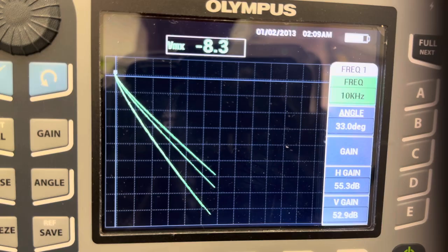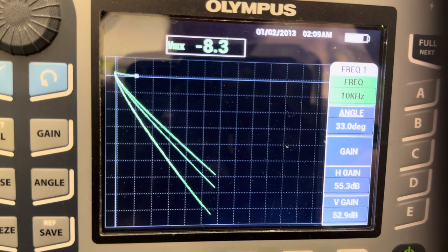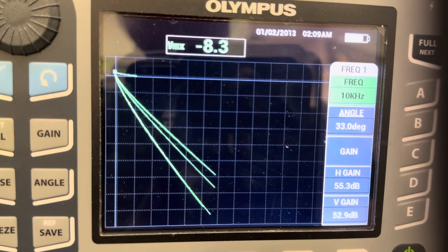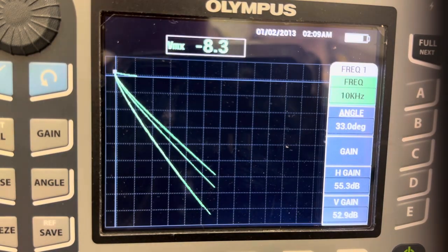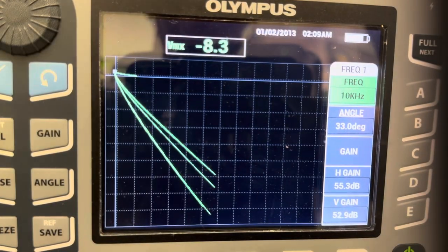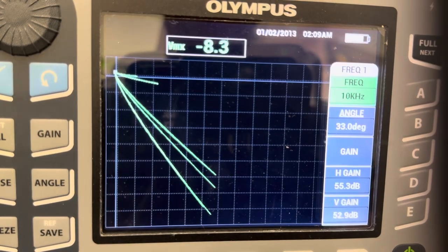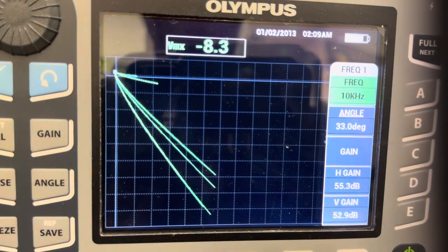But when I try to separate low conductivity materials, like this titanium and then 304 stainless, you see there's not much of a difference there. So if you wanted to sort those two out, you go back to the workstation and run the 2 megahertz.